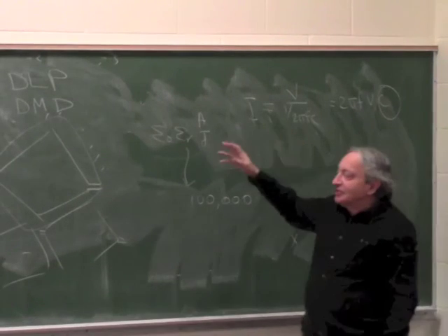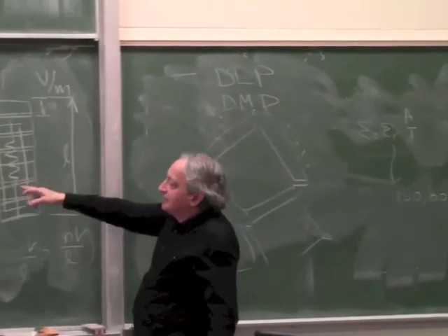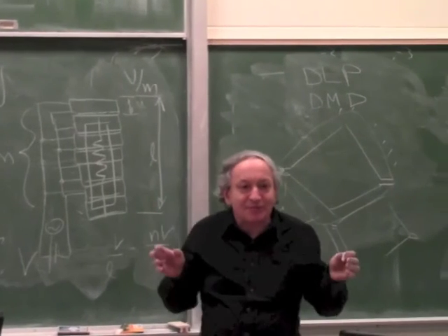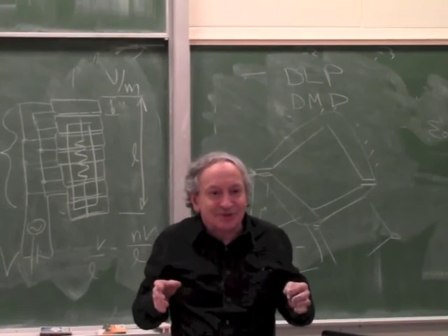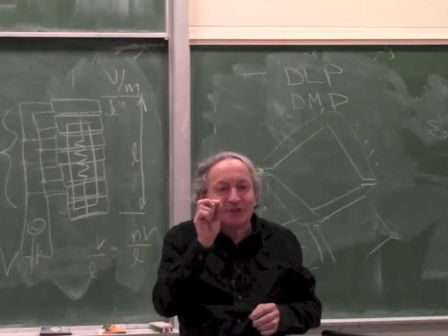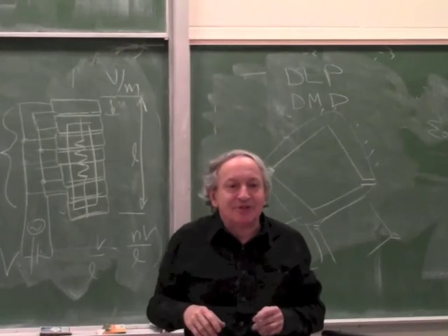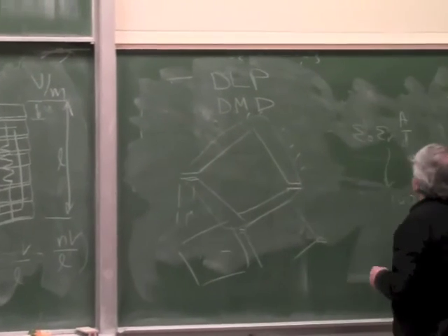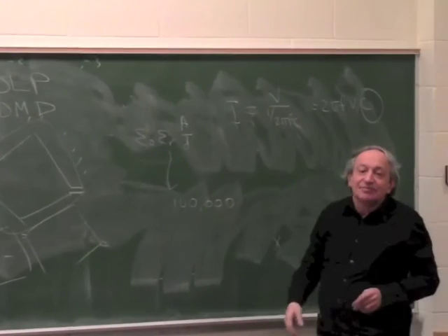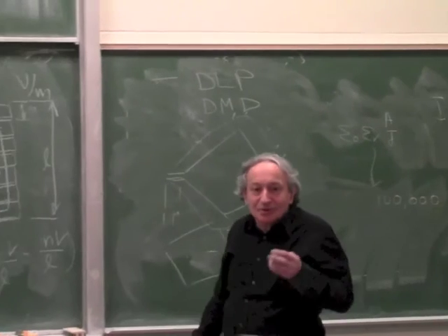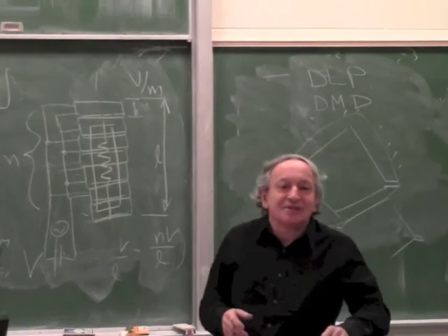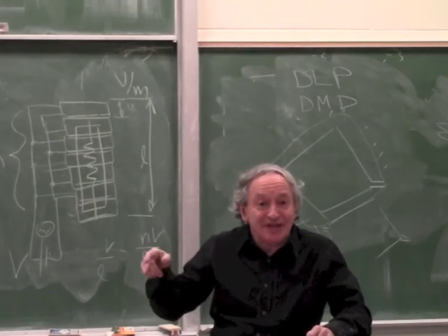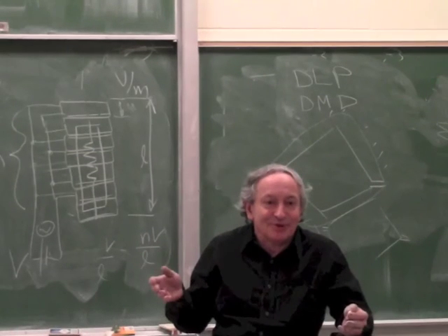So on first sight it looks like it's a perfect actuator. You linearize it with a strain gauge and it's a monoblock. It doesn't have any hinges or moving parts. In practice it's not very useful. It's useful when you make very miniature things, but as a bigger actuator it's pretty useless, because you find right away you cannot drive it fast anyway, because the capacitance ends up a huge number. But on the other hand, the magnetic actuator you also cannot drive very fast, because the inductance ends up a big number, like 2 pi FL. If you drive it at a very high F, you also have a problem.